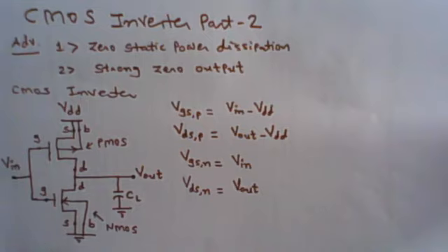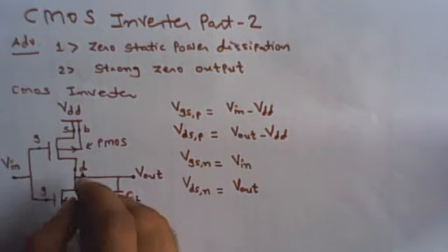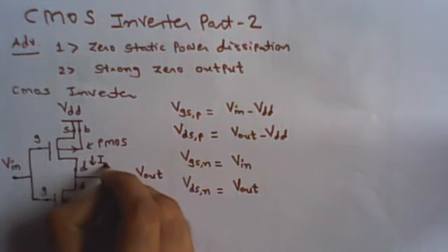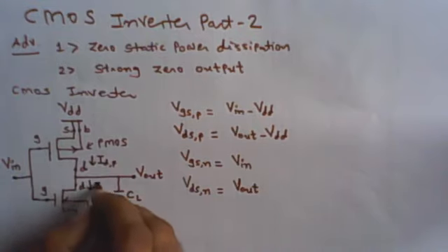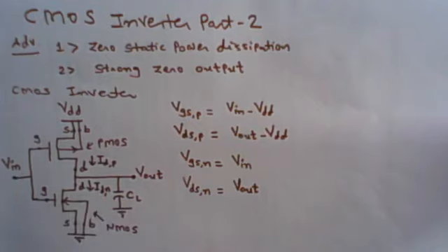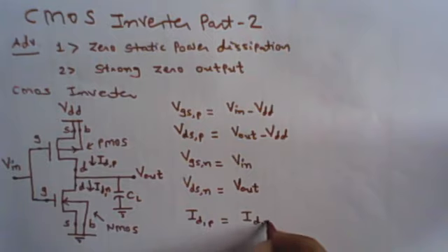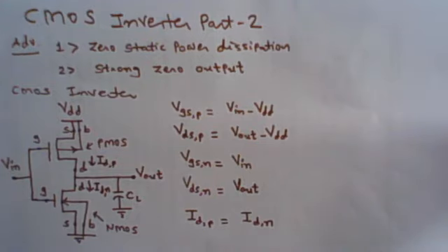Right? Now here we want to analyze the noise margin of a CMOS inverter. To analyze the noise margin, we can see that the drain current of the pMOSFET is equal to the drain current of the nMOSFET. To find out the operating region of the pMOSFET and nMOSFET to derive the critical voltage, let me quickly revise the conditions for the operating regions of the MOSFET.